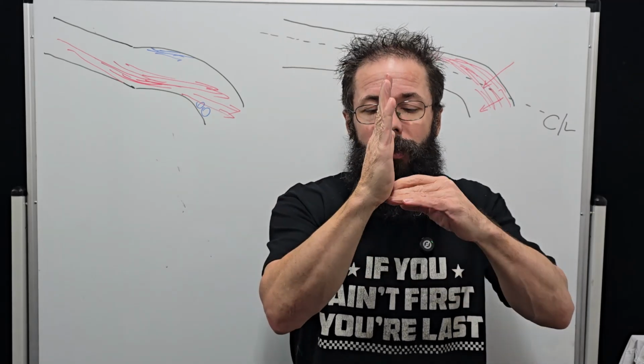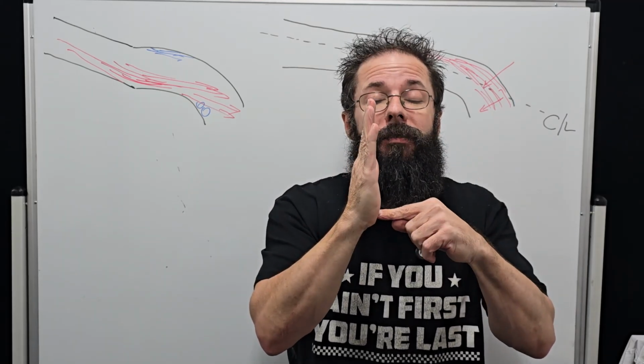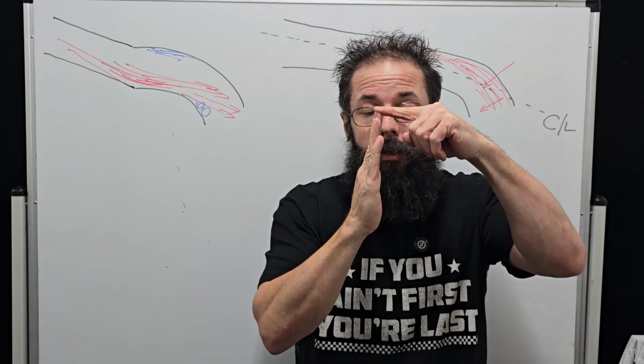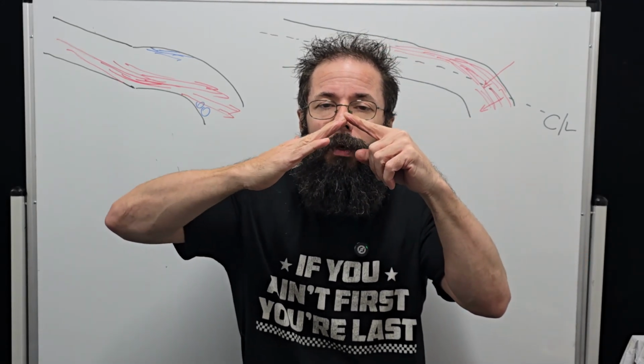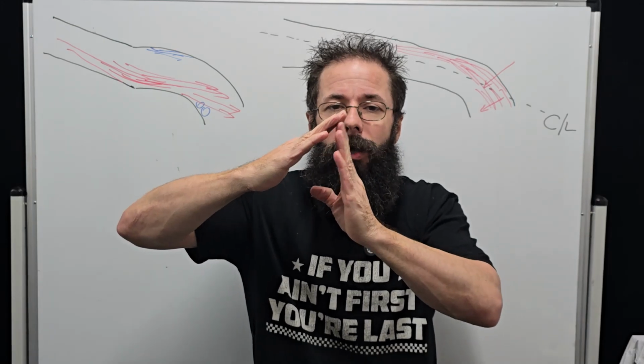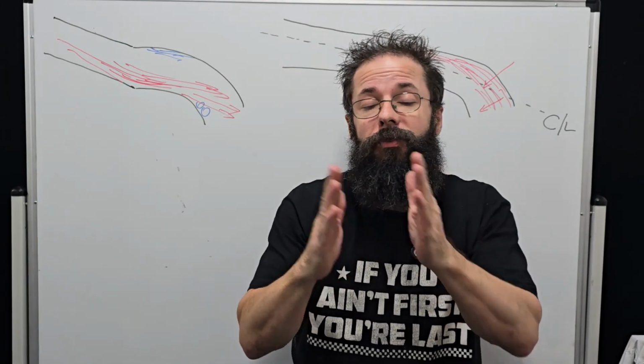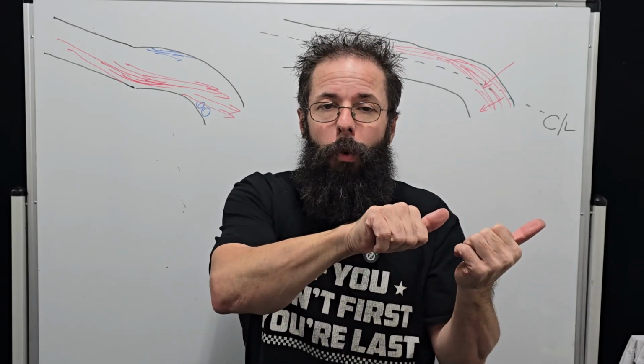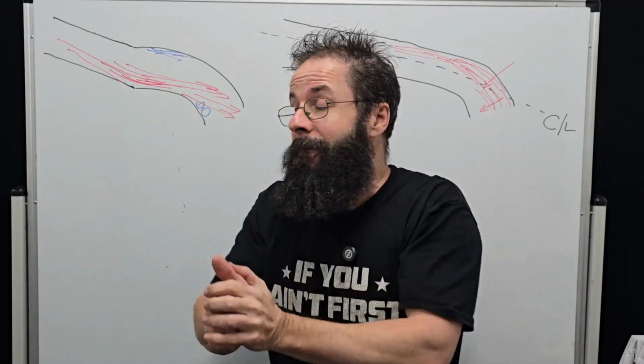So instead of the density being vertical in the car, with the most dense gas at the floor of the car and least dense at the roof, as soon as we accelerate we get this happening. Hence why the balloon wants to go forward, and vice versa around the corners. When we turn into the corner, the dense air goes that way, the balloon goes that way.